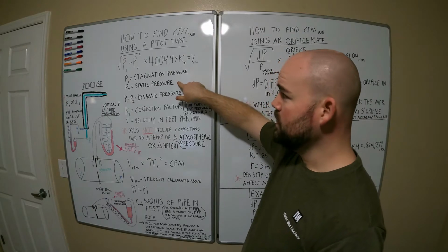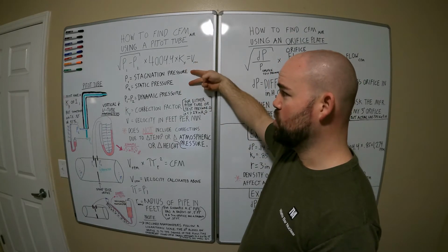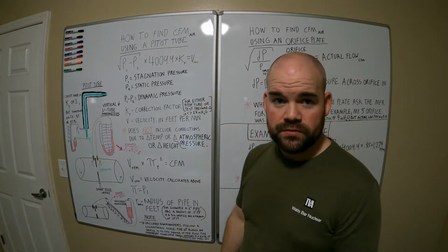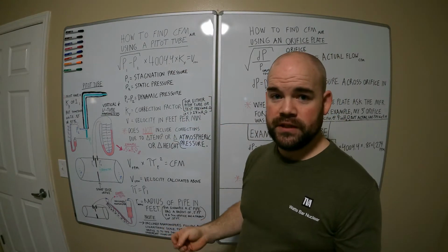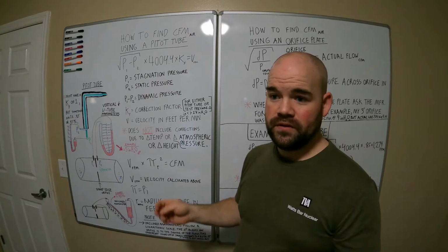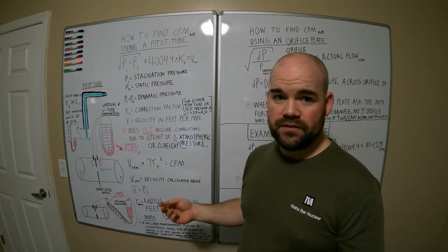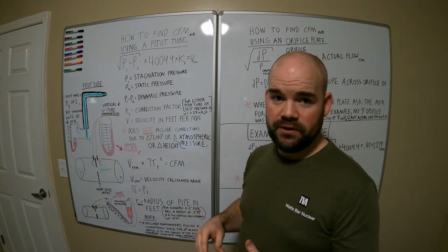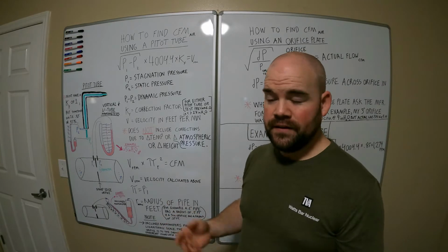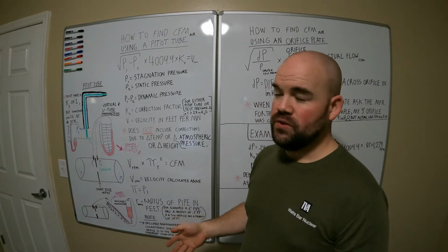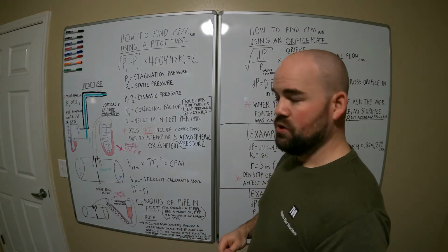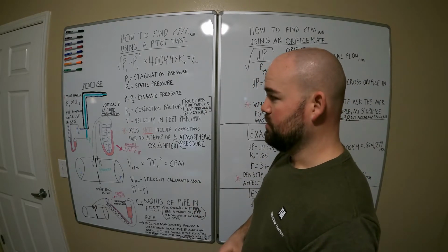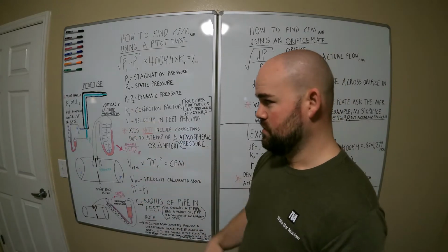Now, where this is important and where you can do this at home cheaply, go to the store, get you some plastic tube. You can put water in it with colored dye, or Dwyer cells, the 0.825 or 0.82 something specific gravity red gauge oil. I recommend that. That's what I use in my manometers. But you can use water if you're on a real tight budget.